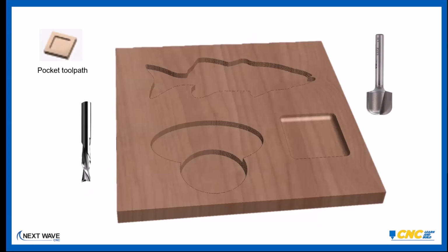Most often it is used with a straight bit, but if you're using it to cut out bowls or trays, you can also use something called a radius end mill, which is on the right side there, which has a flat bottom. Sometimes these are referred to as bowl bits. You can see the pattern there where it leaves a nice radius on the inside. So that's pretty handy also. But that's your pocket toolpath for doing mortise type cutouts.